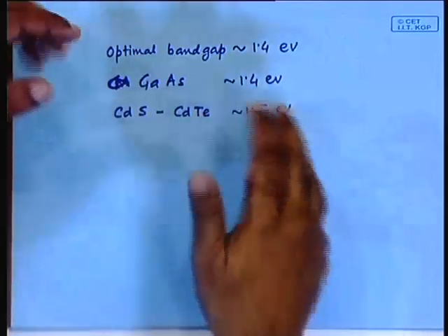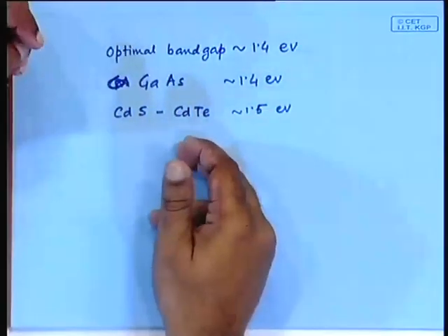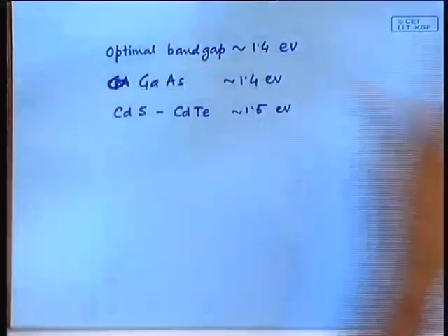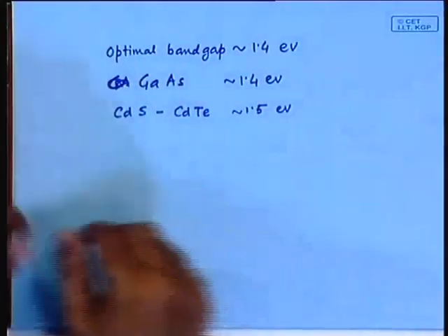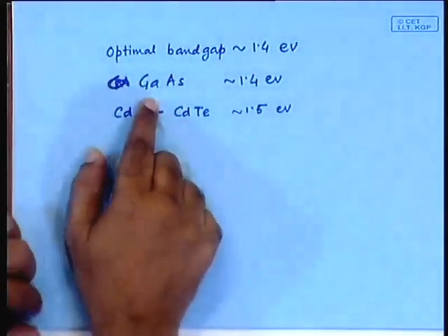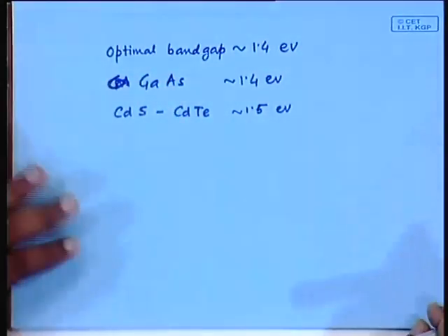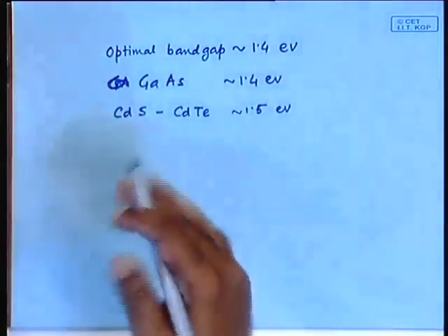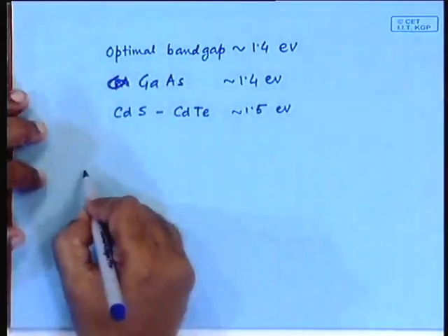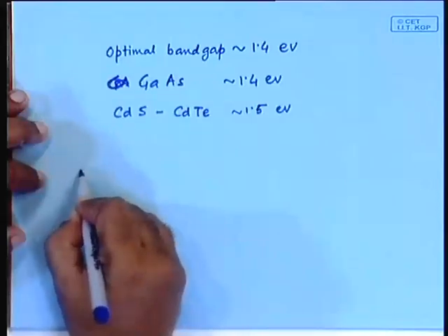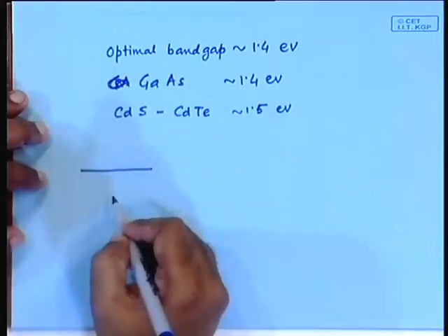Okay. Now, in case of gallium arsenide, one speciality is that temperature does not degrade the characteristic. Mostly, because gallium arsenide is more expensive than silicon, we never think of making very large areas of gallium arsenide, but people do consider concentrating solar cells made of gallium arsenide. The whole scheme would be where you have some kind of concentrator.